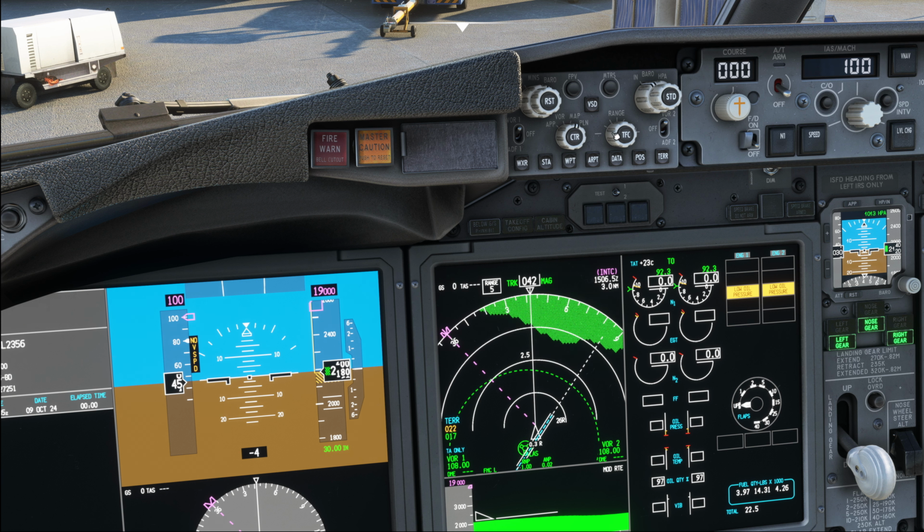Select the display range as needed, and note that the range is shown on the top left of the nav display over here. The idea behind this is that in the 737 MAX you can zoom into a much lower level than you can on the older 737 NG, which is useful if you've got the airport maps on your navigation display, which however at this time is not modeled by iFly.